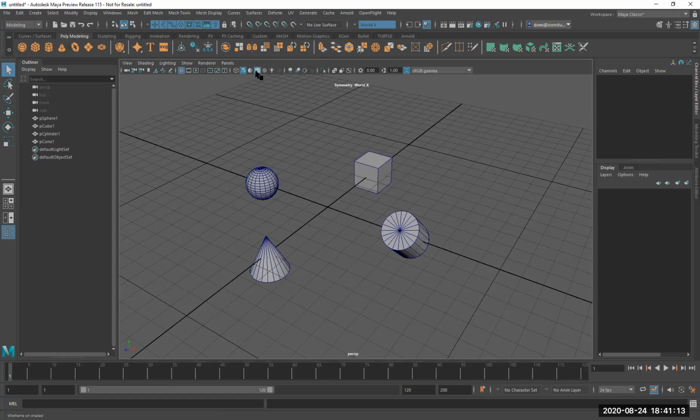Those will be pretty much the ones we're going to be using right now. And don't mess around with these too much right now, because you don't know what these are, and you might get confused later, like, what did I do? So try and stick with just these 4 I showed you: grid, wireframe, shaded, and wireframe on shaded. Okay. And like I said, I'm just going to keep it stepping through very basically. Okay. Let me switch that wireframe off. All right. So that's our panel toolbar.